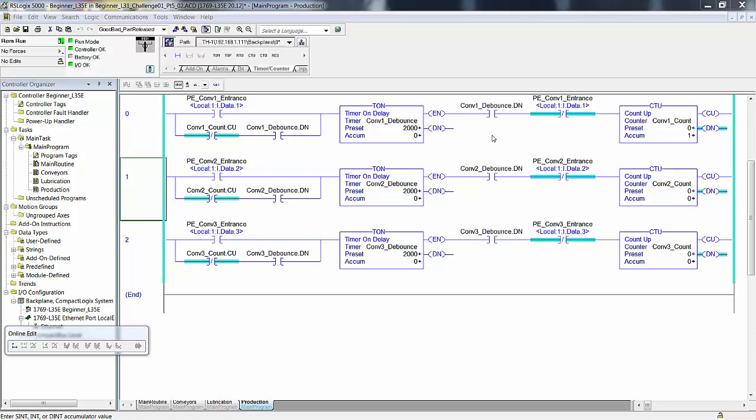Let's do conveyor 2. Push button in, out, in, out. You see the state of these two changing, right? That's the same memory location. What that means is that the switch in executes the first half of the rung, and once it's done, you let off. This goes true, counts up. The count up bit right here undoes the whole rung. You have to watch real quick. I doubt you're going to see it. No, all that you see is things go false and it counts up.